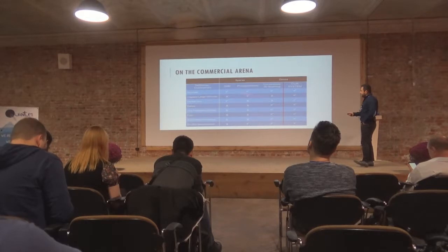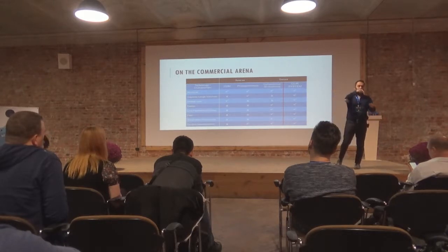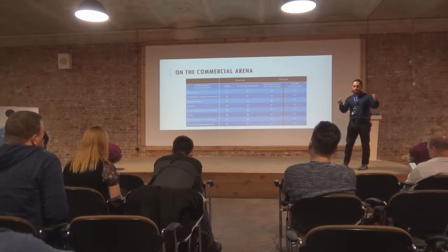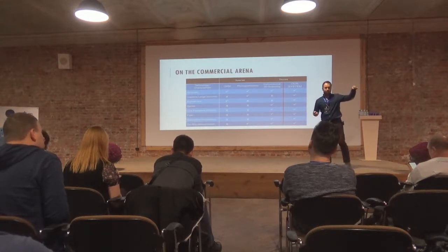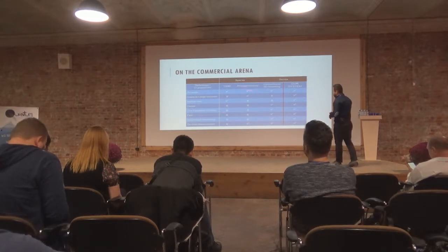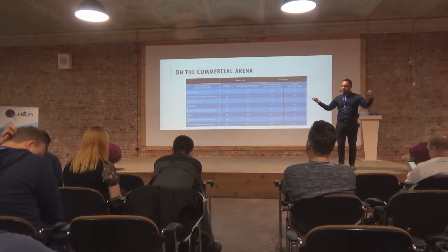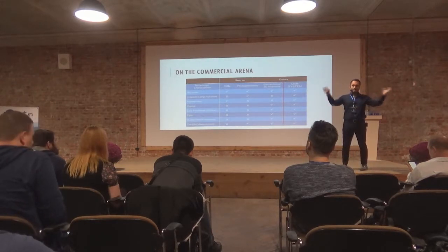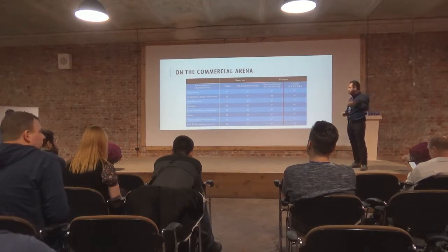Right, so the conventional approach is a CMM machine, so you have to take the part into a machine completely, and you touch different parts of it. So just by touching, you get coordinate measurements, right? Because you know where you touch. This takes an enormous amount of time because you need a probe to touch everywhere to get points. There is photogrammetry. This is very nice, very accurate. You can stick things on the surface and do some optical inspection from images. But this time you don't get a dense reconstruction, right? You just get some points in space, and you hope that these are sufficient to justify your measurement.